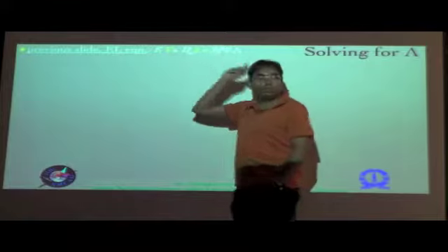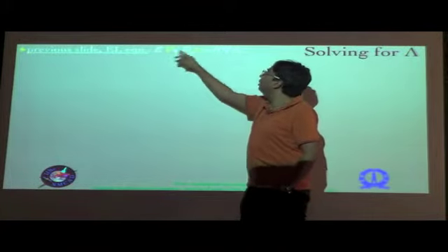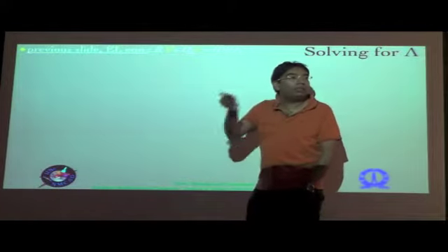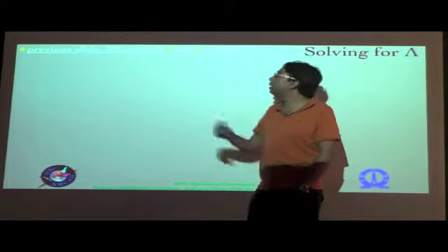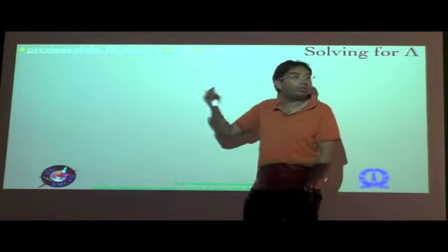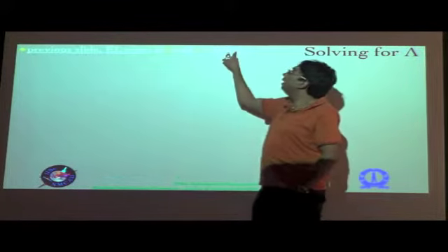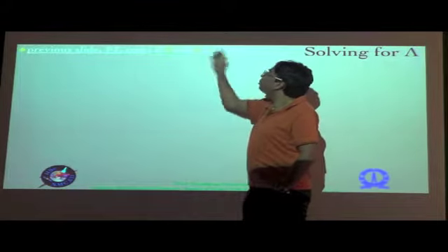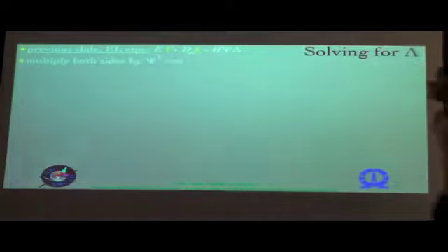So in the previous slide we wrote the Euler-Lagrange equation, which was the governing equation for the V's, to determine the V's in terms of epsilon bar. Because it is discretized, it's not appearing in the usual form that you see as a differential equation. Instead, it's an algebraic equation that has to be solved. But there are two unknowns here, V and lambda, and you have to solve for both of them. Epsilon bars are assumed to be known, though of course they are the 1D strains.